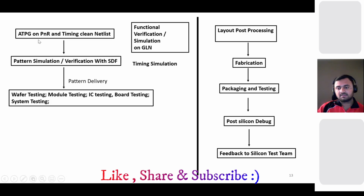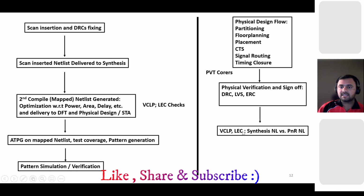So here the physical design team will generate the PNR netlist. I mean the timing closed, placed and routed final netlist they will generate. So whatever you are doing earlier is not the final. Final always happens on the PNR netlist, which the PD team gives, because ultimately the PD team gives the GDS file, which goes for manufacturing. So we need to do all the things with respect to this PNR netlist.